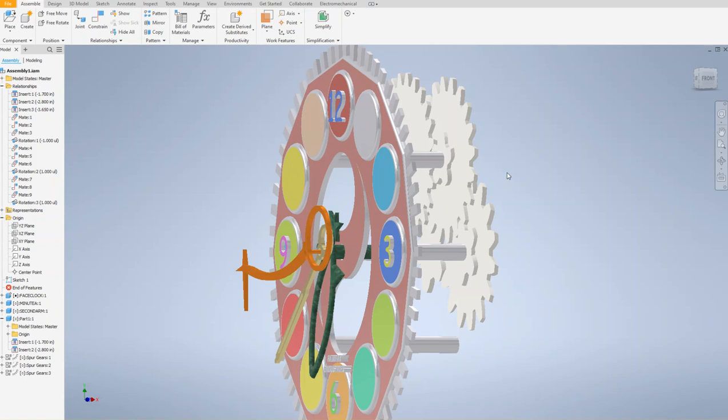So we broke down the entire mechanical advantage of 60 into 3, 4, and 5 mechanical advantages. When you multiply the 3 of them, you get the same number, 60 again.